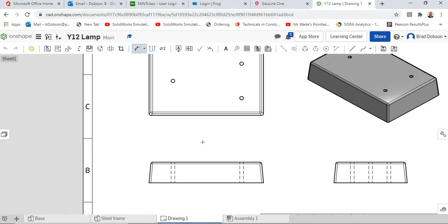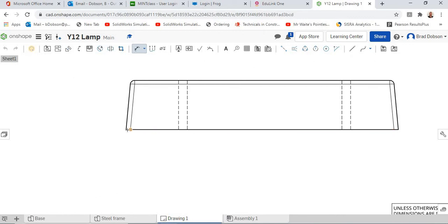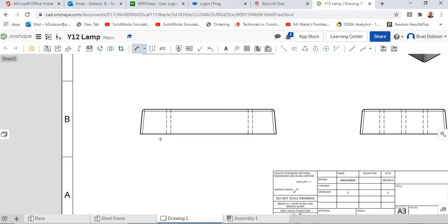So I'm just going to zoom in a little bit and we'll start adding the dimensions on. All I'm going to do, again, is select the very outside. If I just selected that, you'll notice if I zoom in that it's not actually going all the way, because we've got a curve on the end there. So this is where you've got to use, and again, you can do the same for any dimension, I'm just going to select this very corner, go to that corner, drag out the dimension line, and try and get the number in the middle,